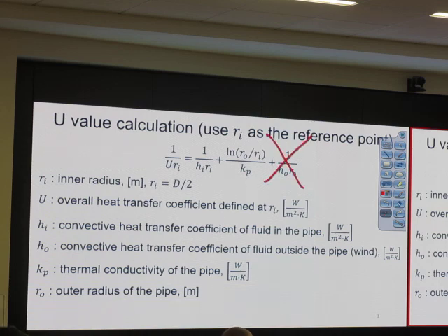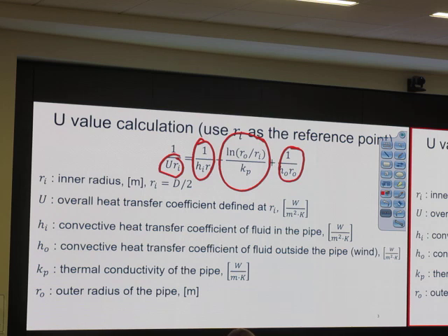So this is telling me that the U value is restricted by the lowest heat transfer process. If I have inside heat transfer very high, that is zero. Outside heat transfer very high, that is zero. This means the U value is dependent upon just heat transfer across the pipe. Okay, this is a pipe without insulation.